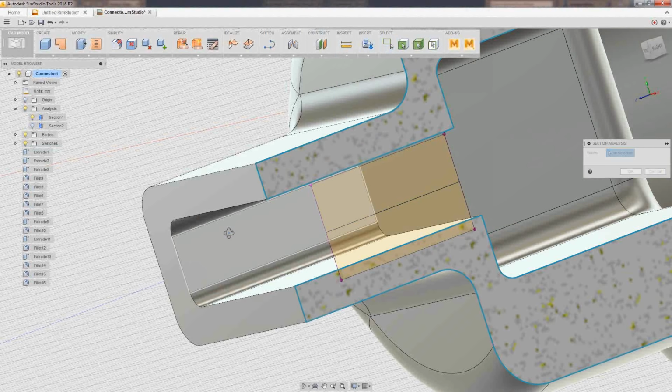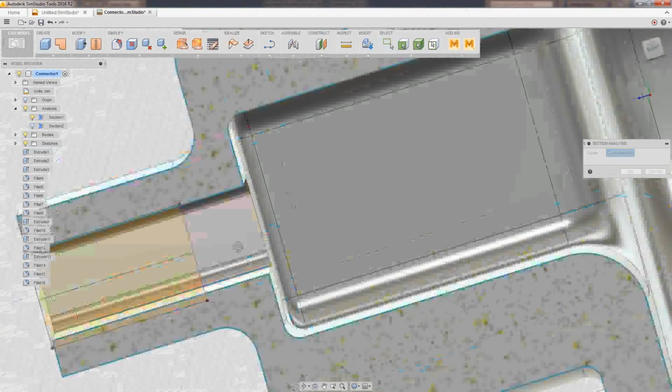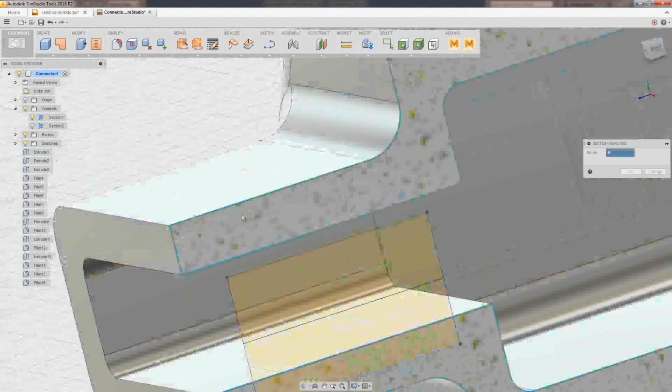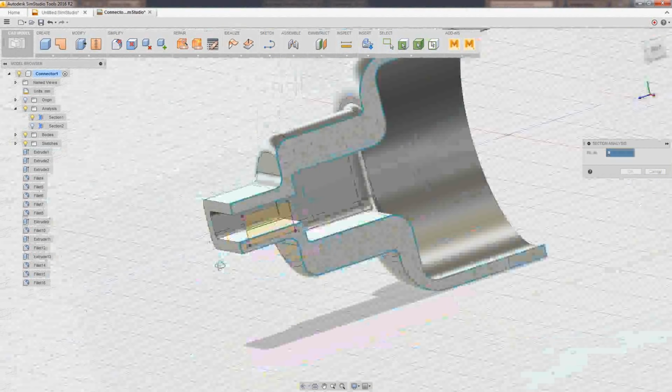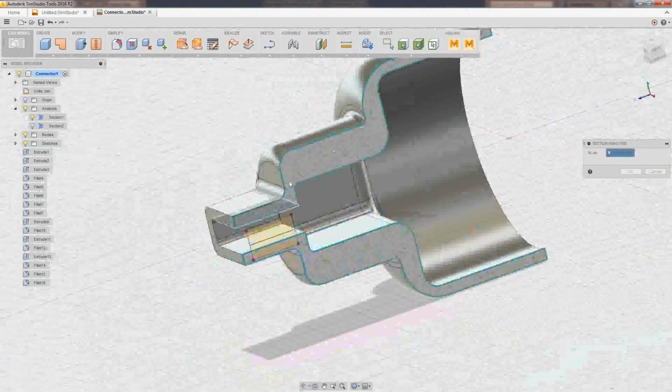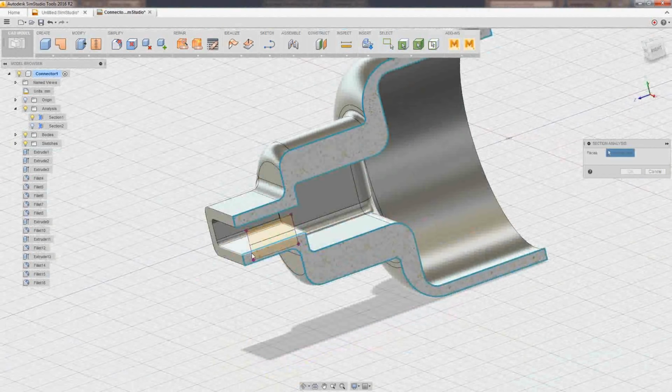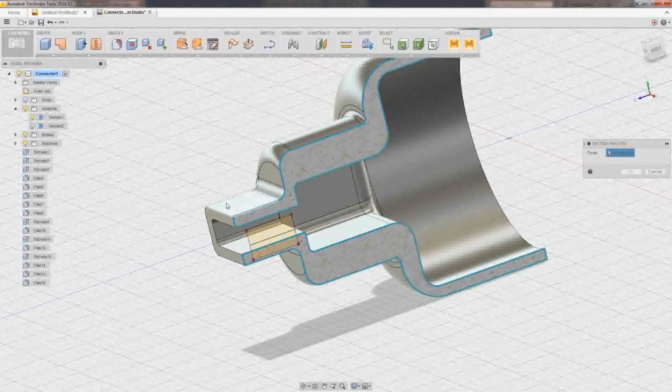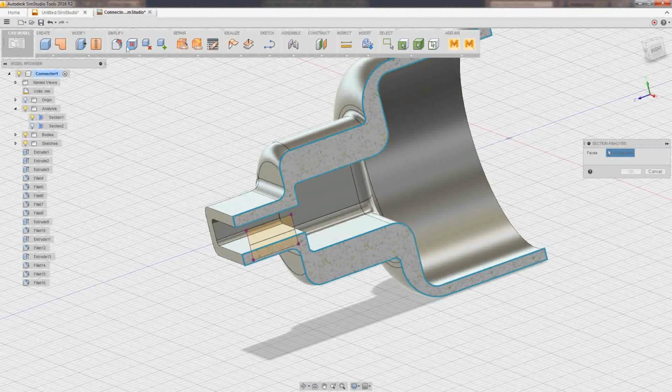If you saw our webinar on SimStudio Tools maybe about a year back now, James went through and showed this in greater detail and described that when you're working with a surface body, this will actually show as hollow instead of filled in like this. And it's a neat way to, one, tell if it's solid, and two, tell if your part's complete and if the thicknesses match up.